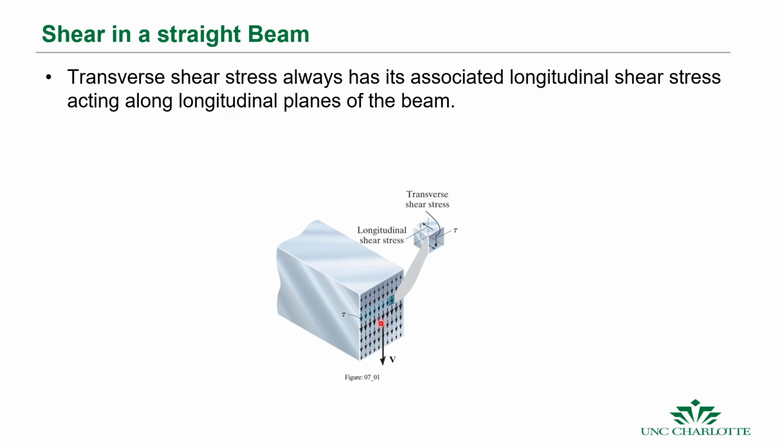Okay, so shear, we have when we take a cross section of a transversely loaded member, and that shear acts across the face. If we were to take out one of these points inside of a cross section, we have this force, the stress across this area. That stress times the area is going to be a force, a downward force. It has to be counterbalanced by an upward force. And those two forces on the front face and the back face create a couple or a moment that has to be counteracted by these longitudinal shear stresses at the top and bottom faces.